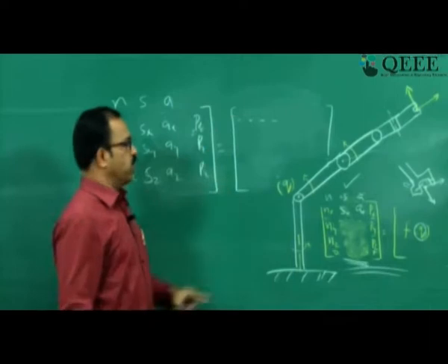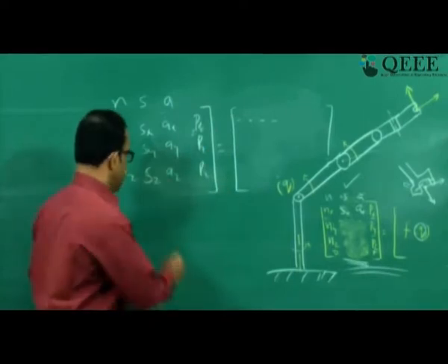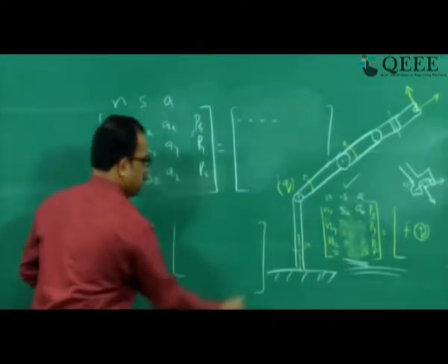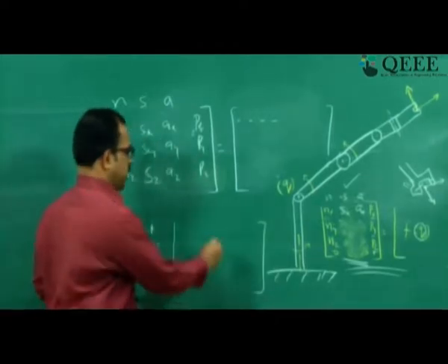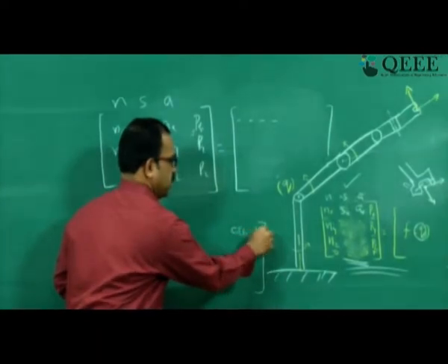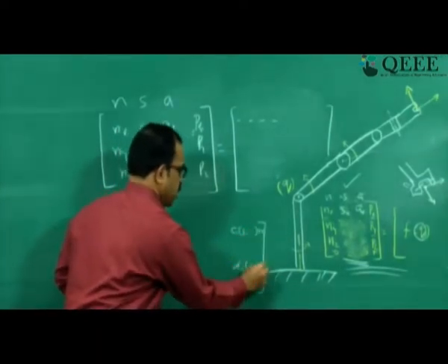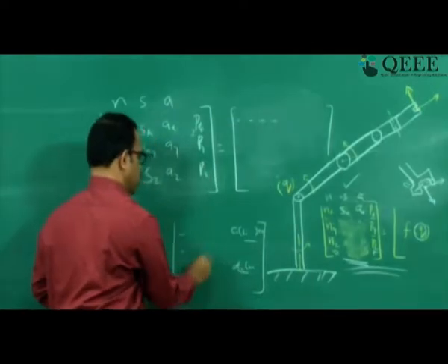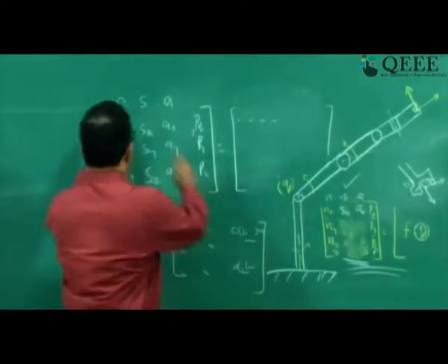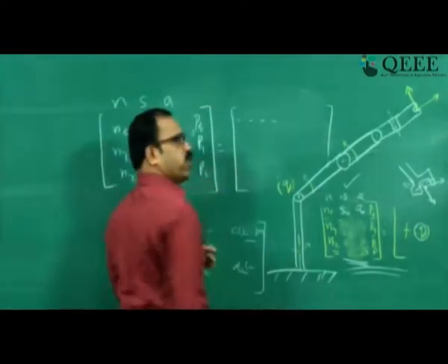You saw that in the forward kinematic relationship, when we do this T2 to base, you will get a matrix in terms of joint variables, like C1 multiplied by S1 something plus D1 cos theta. So this is the way you get the relationship for each one. The inverse kinematics problem is solved by equating this to this and then trying to solve for the joint variables.